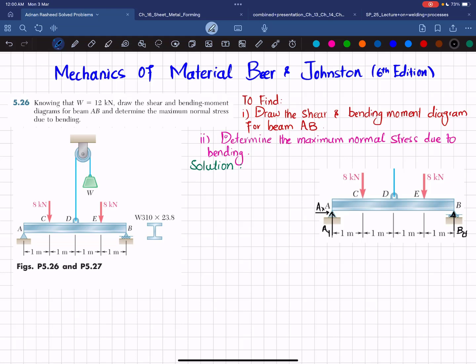So the first equation of equilibrium is that sum of all forces along x direction must be equal to 0, and force toward right is taken as positive. So AX is acting toward right, and there is no other horizontal force, so it means that AX is equal to 0. Now we'll find this another force, which is AY.